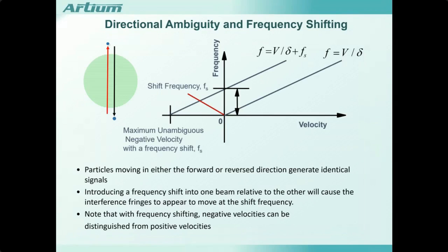Another characteristic that needed to be resolved was the directional ambiguity of the measurements. In my work at NASA, I was working in transonic and supersonic turbulent boundary layer separation. In those flows, you could have velocities of 300 meters per second in a positive direction, and in a few millimeters or less lower, you could have negative velocities at 100 meters per second.